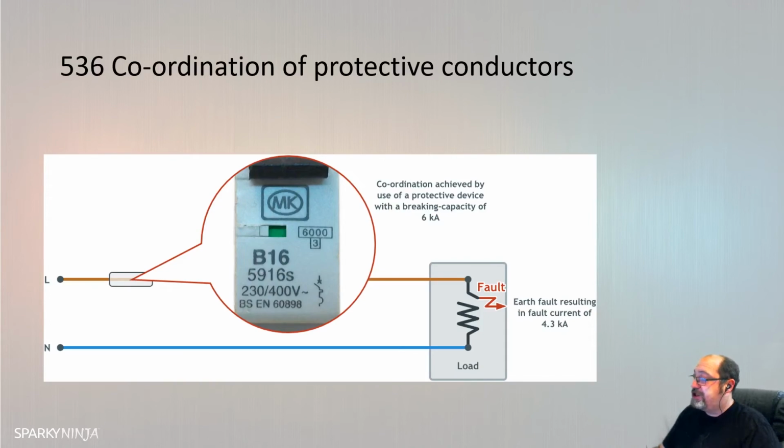536, though, coordination. Yeah, this talks more about the need for effective decision making. So the section covers coordination in the case of fault and overload conditions, and also takes into consideration aspects of section 133 relevant to the coordination of electrical devices as follows. Let's remind ourselves of 133, which was a fundamental principle. That is the general selection of equipment, appropriate British harmonised standard, and then you've got the characteristics, voltage, current and frequency there.